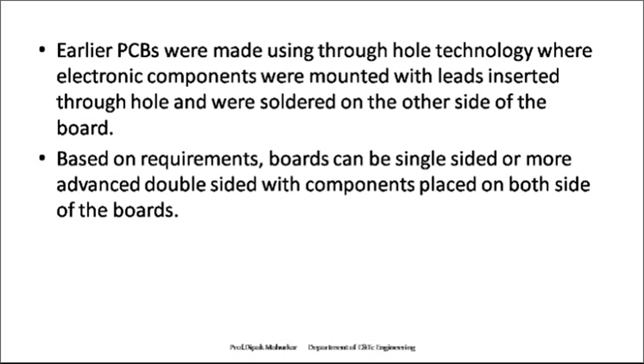Now, these are the old technology. Nowadays machines are available. Just insert the PCB in the machine and push the button. Then automatically the spray is fired on the PCB, and where the tracks or paths do not exist, that respective copper will be removed. So these are the simple ways of designing the PCB.